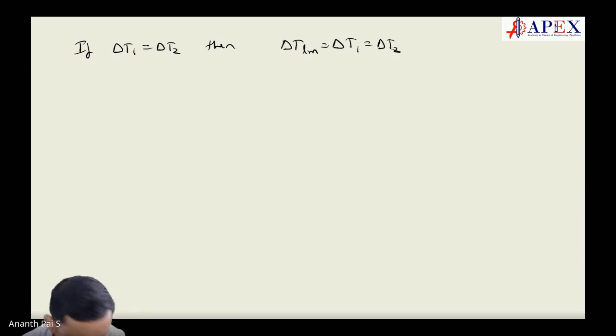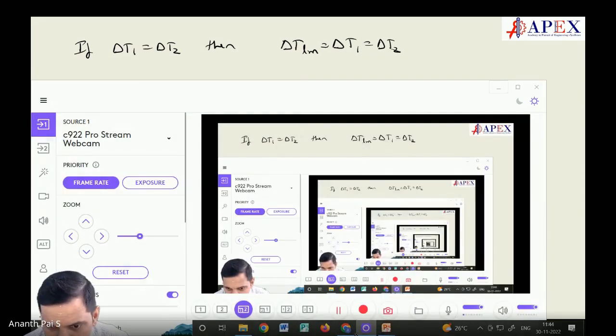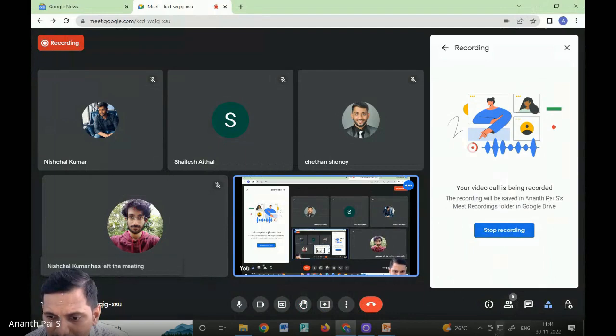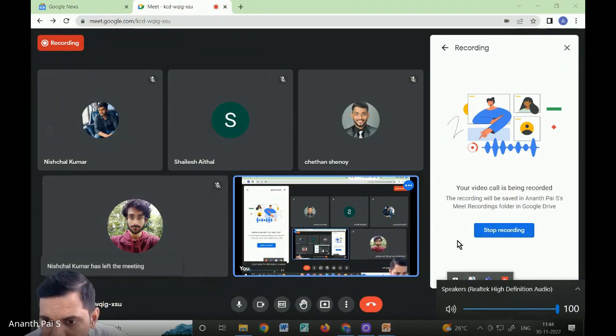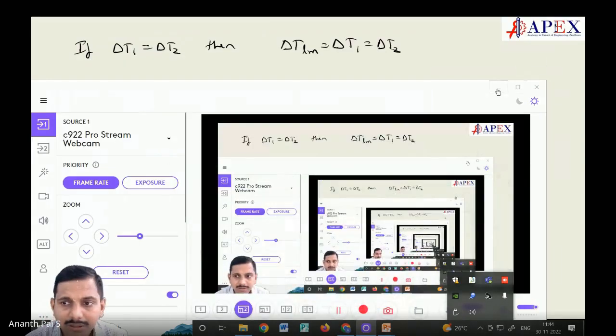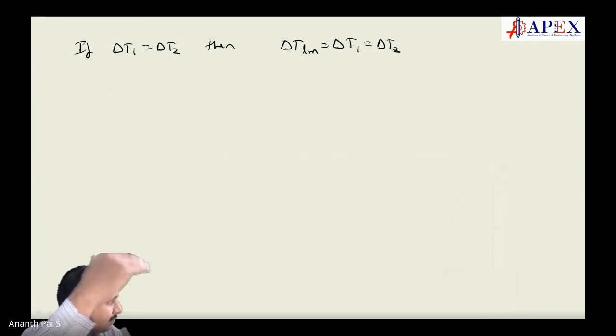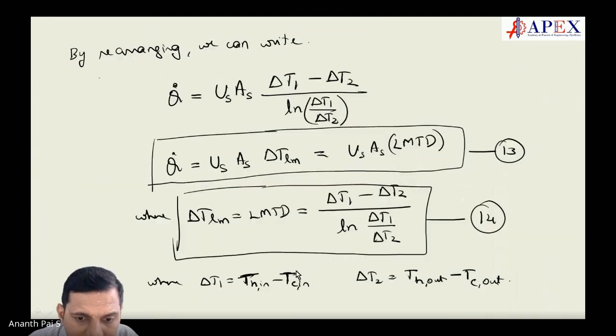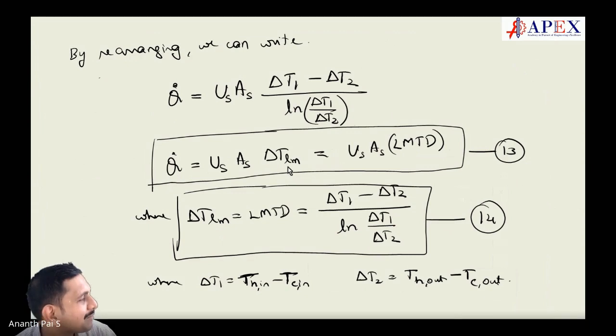Same temperature difference, is it not? So log mean temperature difference, why do we use? We use so that we can calculate the delta T, is it not? So it is mainly to calculate the heat transfer. Observe, delta TLM is to calculate the heat transfer. Now delta T is the same and heat transfer is the same. What is the requirement of calculating the log mean temperature difference?